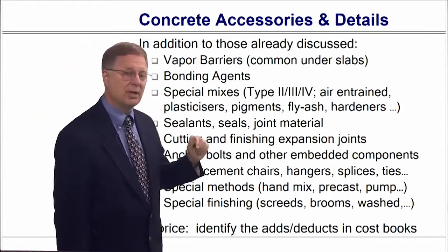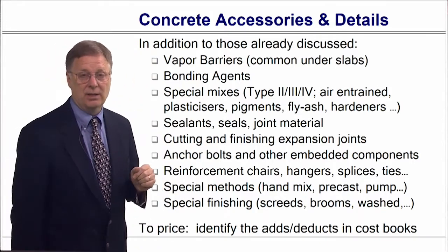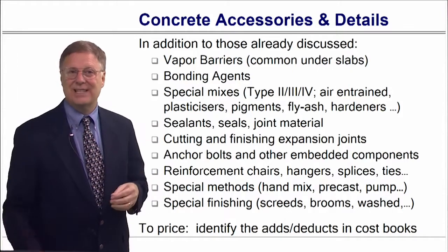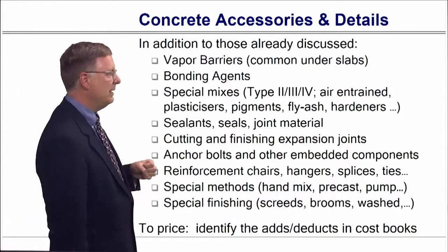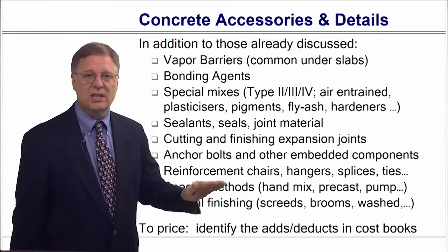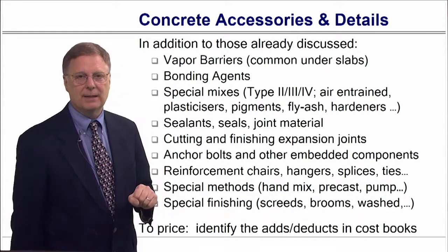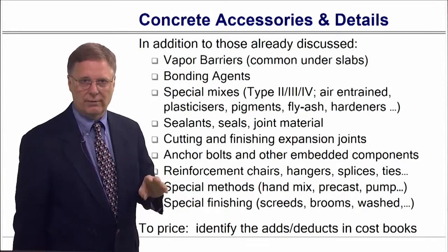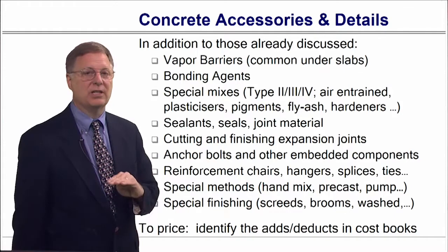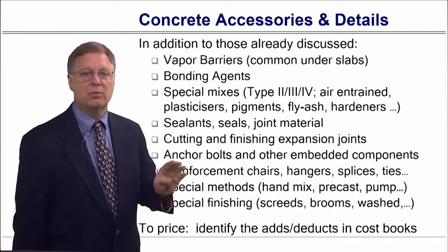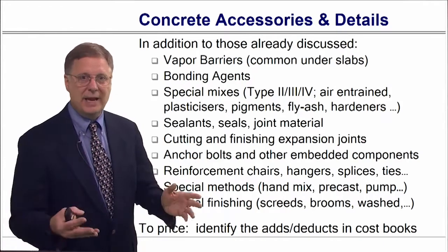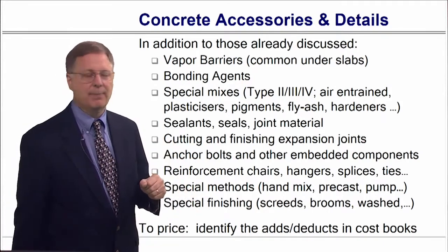Special admixtures, you might have air entrained mixes for a footing, especially because it might experience freezing and thawing. Or there might be special hardeners, or I used to work with a contractor who put plasticizers, or hydrolyzers, or whatever you would call those things, in every mix. The reason is because it saved them so much in labor, and in this area it's relatively inexpensive. It was pennies to save the amount of labor time.